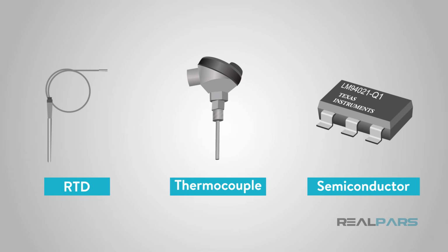To wrap up this video, the comparison between different types of temperature sensor technologies is a multifaceted task. For example, if accuracy is considered as the key performance indicator, usually RTDs are better than thermocouples, approximately 10 times more accurate. From the sensitivity point of view, while both RTDs and thermocouples respond quickly to temperature changes at similar costs, thermocouples are often faster.